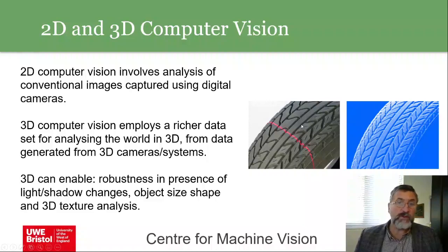And if we're doing that, for example, we could put a filter in front of the camera and match that to the wavelength of the laser we're using there. And in that way, this is what it says here, robustness in the presence of light. This would really help the robustness because changes in background light wouldn't have much of an effect because you're looking through this filter. So that does help, and that was something we do a lot of the time.